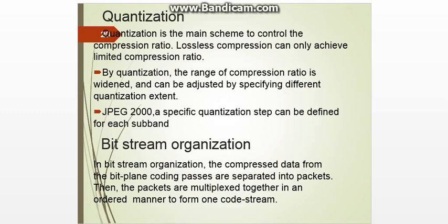After the quantization, entropy encoding is used. The statistical redundancy can be removed by entropy coding. It is a lossless coding process based on the concept that more frequent symbols can be assigned the shorter code words and the less frequent ones can be assigned the longer code words. The average code length of the variable length coded data will therefore be shorter than the fixed length codes. In case of JPEG 2000, arithmetic coding is used.